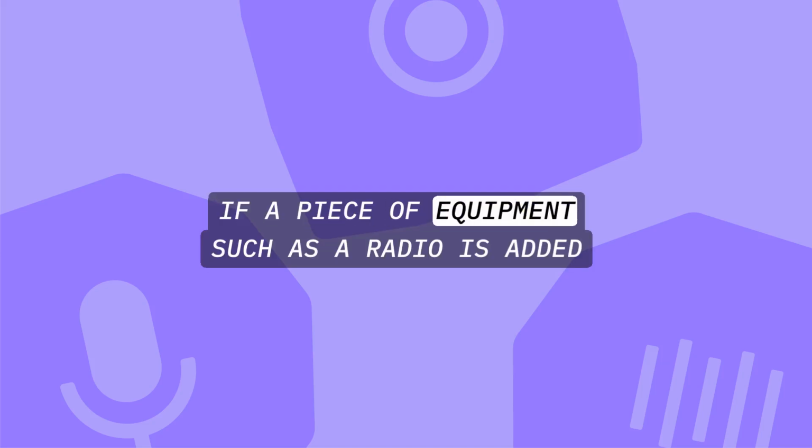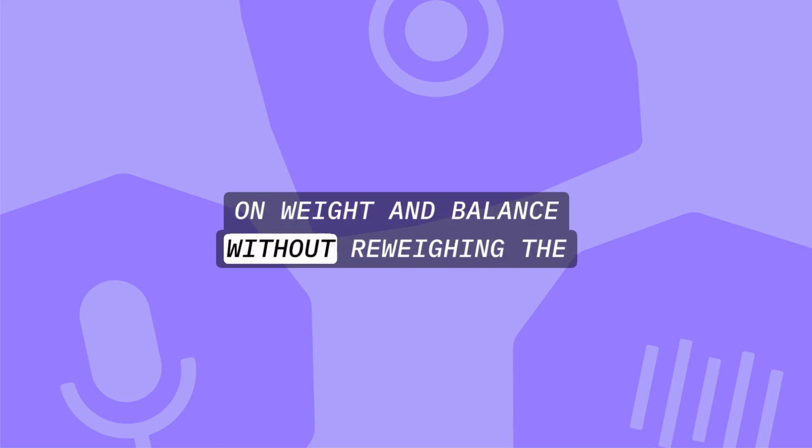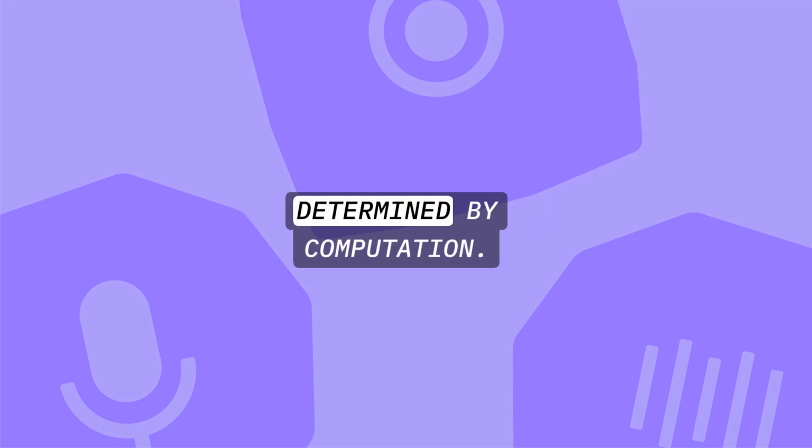If a piece of equipment, such as a radio, is added to an aircraft, how can you determine the effect on weight and balance without reweighing the aircraft? If the weight and balance records are up to date, a new weight and CG location can be determined by computation.